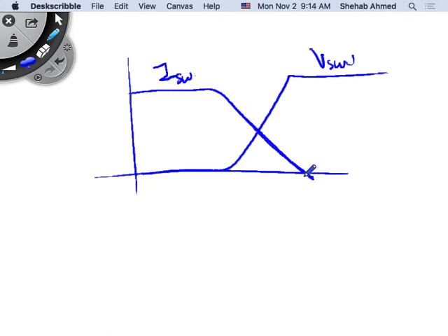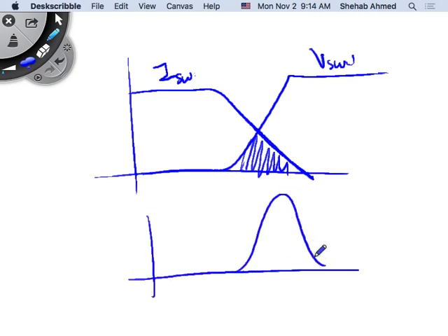There's a T rise and T fall, and voltage will rise as well. So every time you switch, there will be switching losses. These losses depend on the value of voltage and current. So you want to be able to switch fast. How fast will be limited by your switching losses.